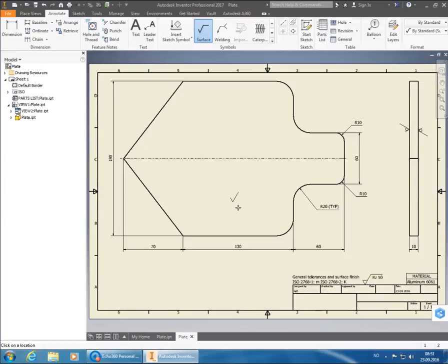And this will tell them that they don't need to use a milling machine to get the correct surface finish of the plate. Because if I hadn't put this one up here, they might have run it through a milling machine, shaving off just a couple of micrometers of the surface, of the top and the bottom, just to get the correct finish for it, just to get it smooth enough.